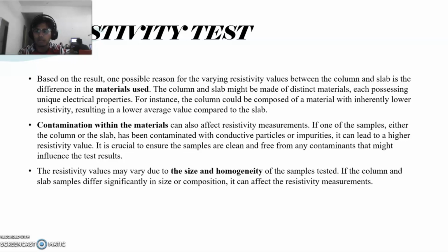And the last, the resistivity value may vary due to the size and homogeneity of the sample tested. If the column and slab samples differ significantly in size or composition, it can affect the resistivity measurement. That's all from me. Thank you.